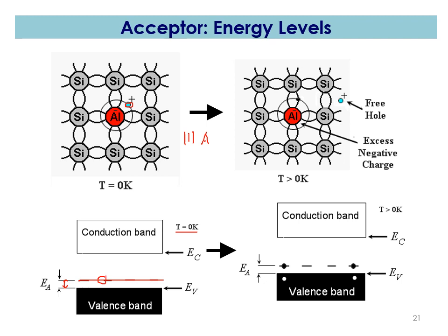At T above 0 Kelvin, the electron from the valence band will easily be excited to fill the hole, and hence it will create another hole in the valence band, and the process will keep continuing, so this kind of semiconductor will conduct the electricity by using the holes, and we call it a P-type semiconductor.